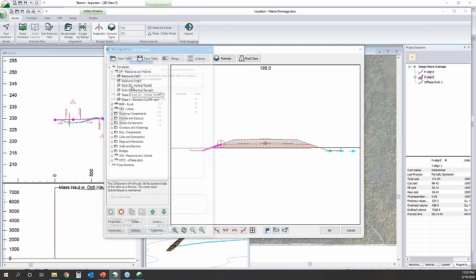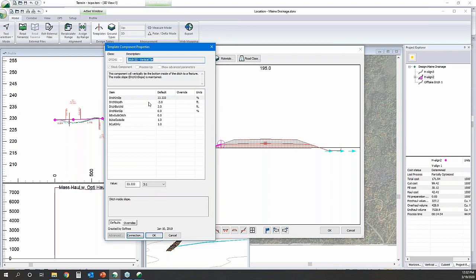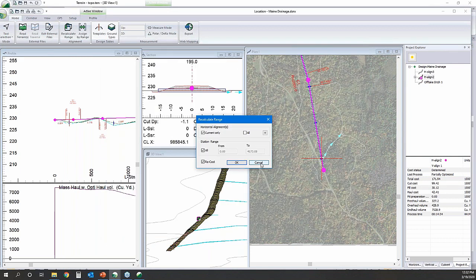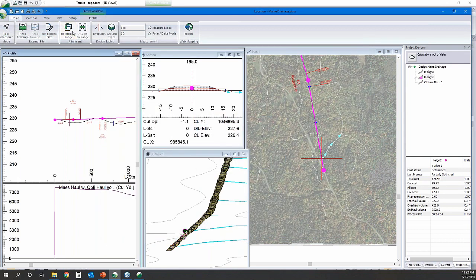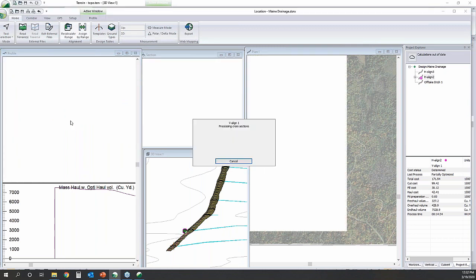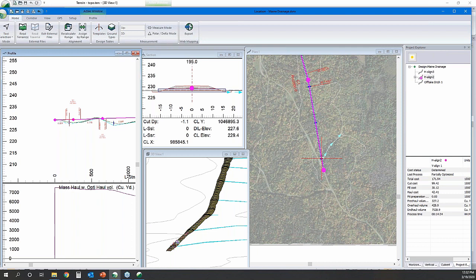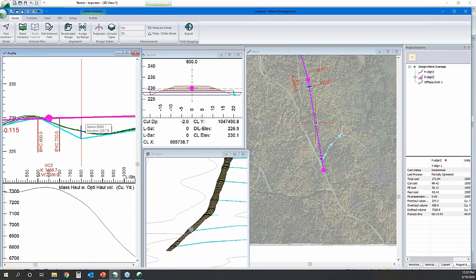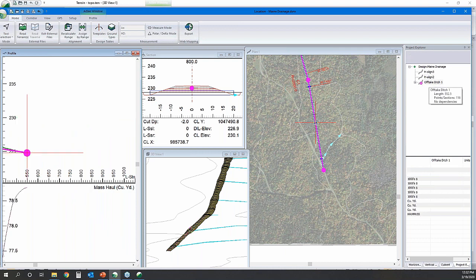But the interesting part here is the ditch template that I used. So I've got a ditch depth that's set at 2 feet unless we have a reference feature, and then it'll follow the reference feature. So this, we're using the reference feature tie. And we can generate a pretty good drainage plan for our flat roads as well. You can take this a step further. You can also use that to plan your off-take ditches.